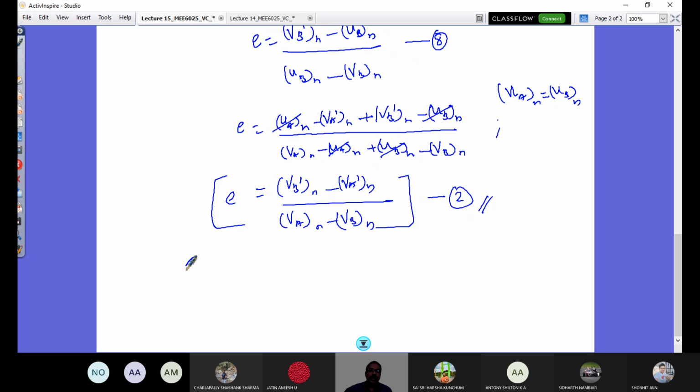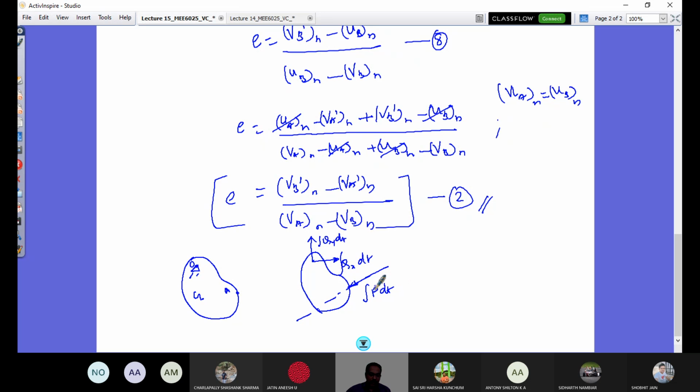So let's look again at this body A, where it is now constrained at this point, hinged, say point O. If CG is somewhere here, and this is the contact point A, right? So this diagram would show what these reactions are. So in the free body diagram, if I draw, this hinge would be removed, and I would have there two impulse force components. So this is integral qx dt. This is integral qy dt. And of course, I would have along the line of impact my deformation impulse, integral P dt.